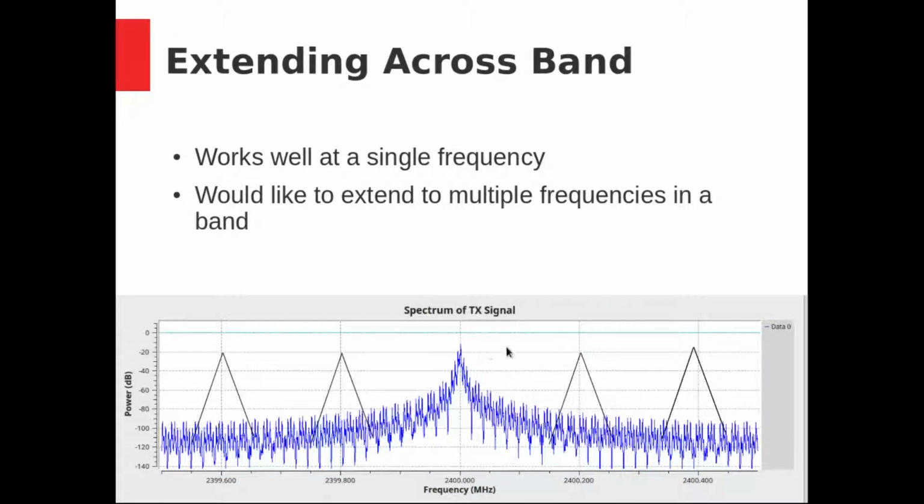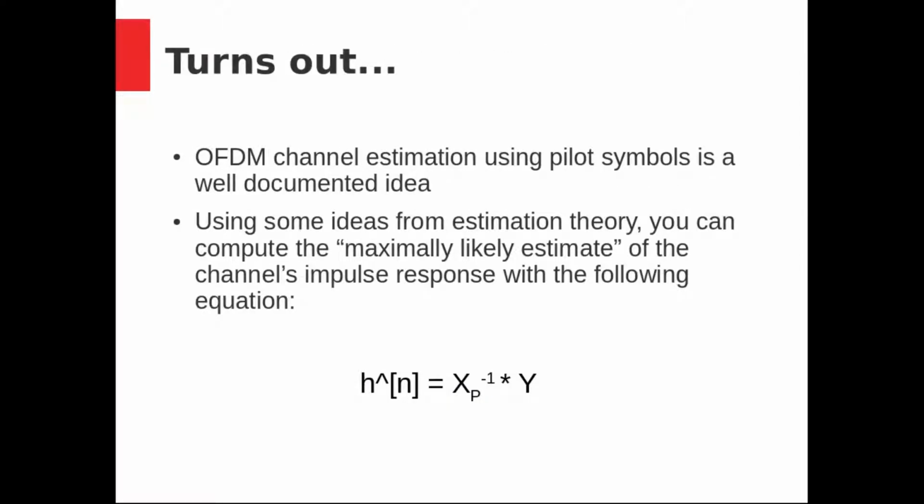The way I'm thinking about doing that is if you just transmit multiple copies at a single time, these triangles would represent other copies of that signal. And on my receiver, I could have a variable center frequency where I could move that receiver around until I aligned with each one of these, calculating the phase shift at each point. As I started looking into doing this, I was thinking about maybe using an OFDM signal at my transmitter so I could get as many of these signals as close together without interfering with one another.